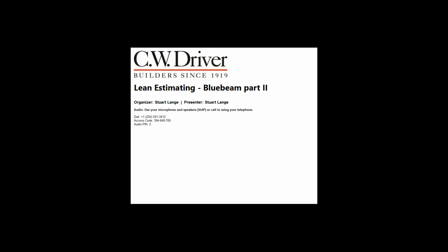So you could just hit OK, that's fine. But if you have more stuff, that's where you change it. Hit Generate, and then that gives you your lists. Once you click Generate on your top right here, you see it makes your list from your page labels. Now this is everything that Bluebeam is going to look for to link to.